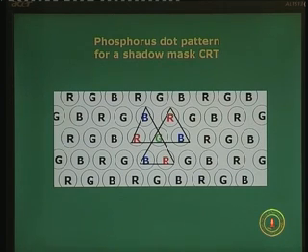So, one such circle is a phosphor dot, and 3 of them form a triangle. There are 3 triangles shown, the top 2 corresponding to, let us say, scan line number 1, or the top scan line, and similarly at the bottom we have another scan line which is also going, and the RGB alternates basically. So, the same G could be used for the next one and so on. The beams have to be changed as you go along. The RGB arrangement becomes, in the next pixel, GB and so on. So, this is how you probably save space.